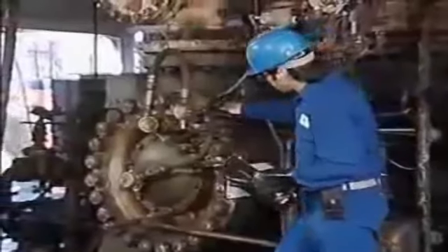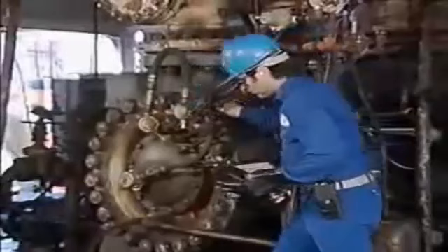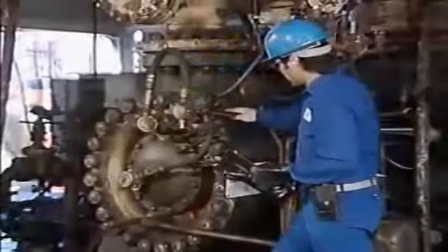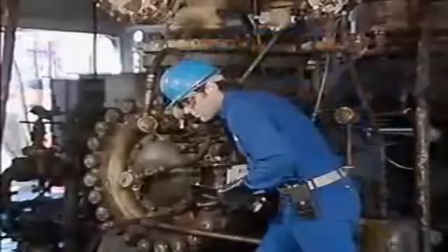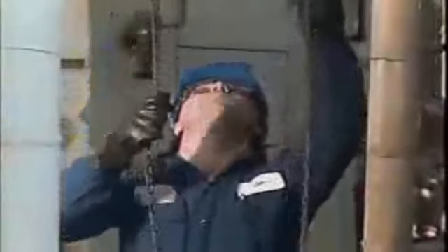Eventually, the compressor will be brought up to its minimum operating speed, which is the lowest speed the compressor can be operated at without causing surge or other operating problems. When the compressor reaches its minimum operating speed, the gas flow to the compressor can be started.